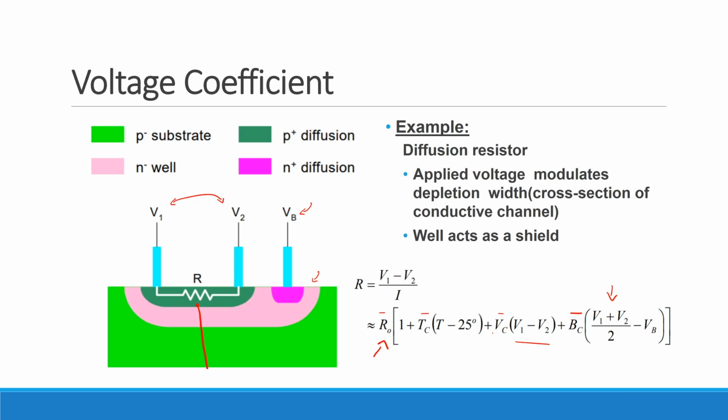If I know what that center point of V1 and V2 is supposed to be, I could just drive that VB to sit right at that center point. Right? Now, by the way, if you were to actually build this, any ideas how you might really do that? I was thinking for a CMOS. Okay. Could you tie one of those ports to the VB, or does that not work with resistors? Well, what do you mean tie one of the ports? Because with CMOS, you tie source to body, right? Right. So, similar here or not really?